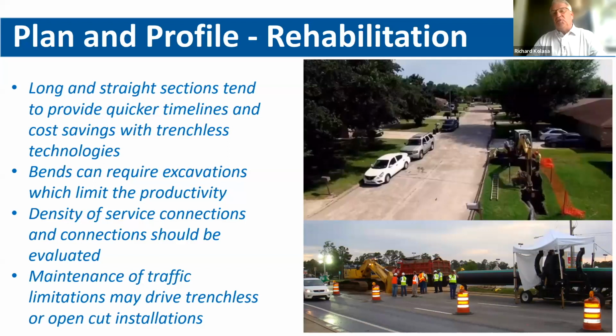Yeah, and everybody, just don't forget, especially in gravity systems, because we've had these experiences in the past, when you go manhole to manhole and you pull that pipe through that manhole, we have all kinds of restrictions on infiltration and exfiltration of those manholes. We have to seal those up a little bit so that doesn't occur, but leave that pipe longer, because when you pull pipe, it extends and elongates a little bit, or the surface temperature is a lot warmer than the soil temperature, so you will get some contraction of that pipe.